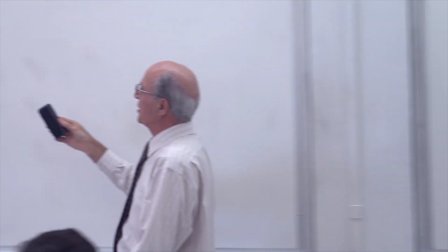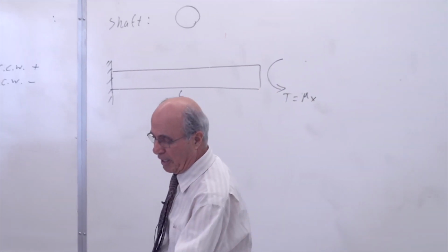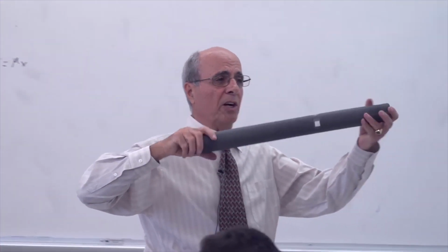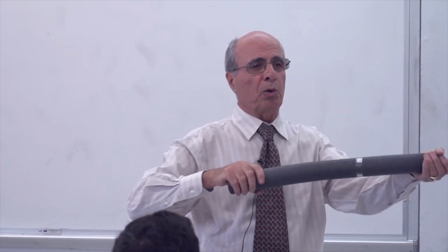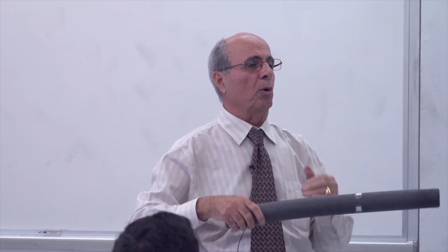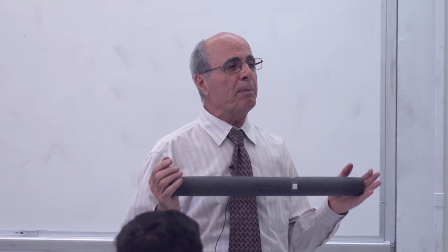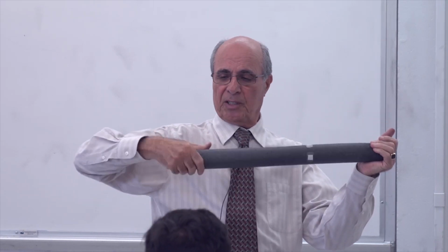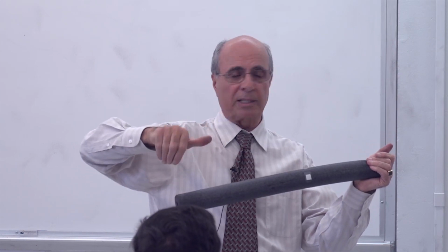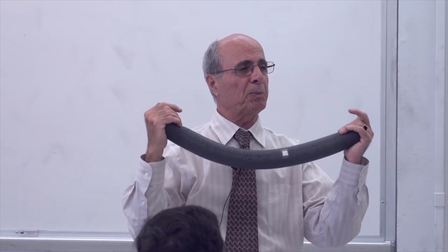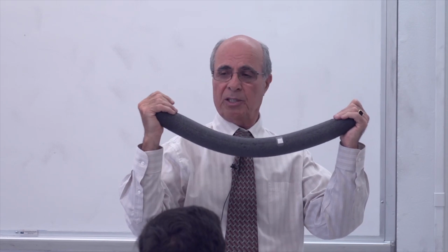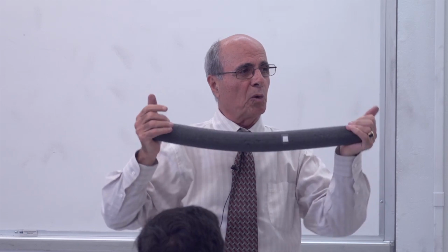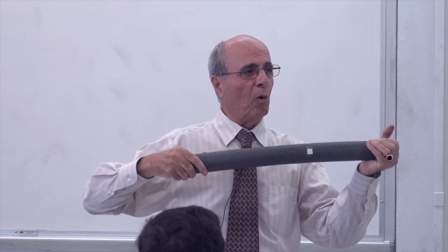So now, here is the scenario. By the way, I have to do one more static there. If you have the rod like that, right now this is the x, yes? This moment, which is Mx, becomes torque, yes or no? The other two moments become Mz, look at my thumb. This is Mx, look at it like that, yes? This becomes torque, this becomes bending, which is, look at my thumb, Mz, and this one becomes My. So we have two bending and one rotation.